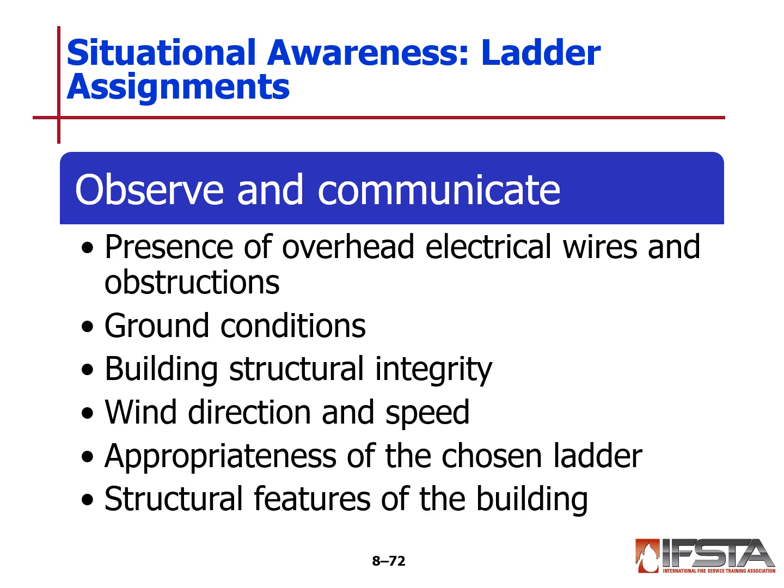On a real windy day, it can be a challenge sometimes to get extension ladders deployed. Consider the appropriateness of the chosen ladder. We want to make sure, again, is this the right ladder for the job at hand, the task at hand? And then consider any structural features of the building that might complicate things.